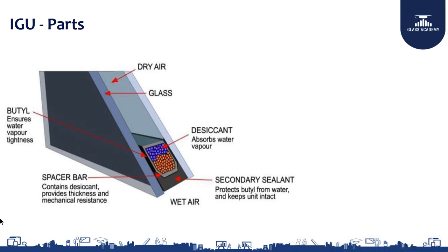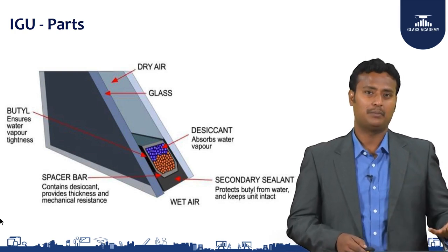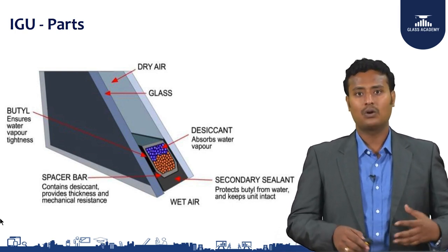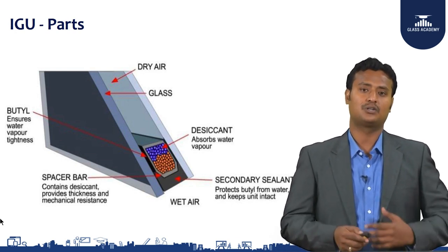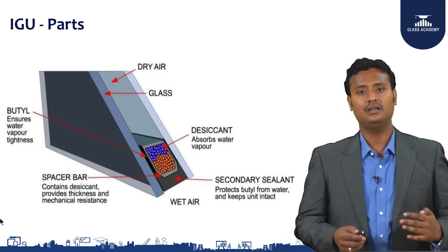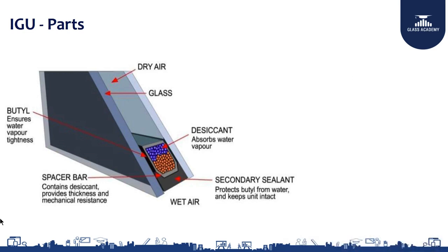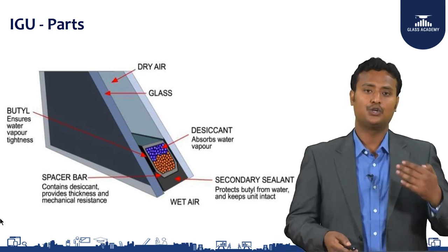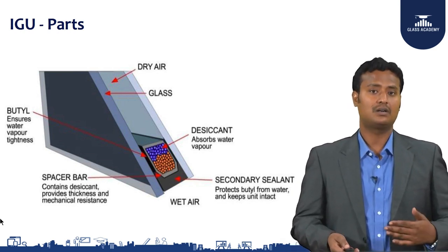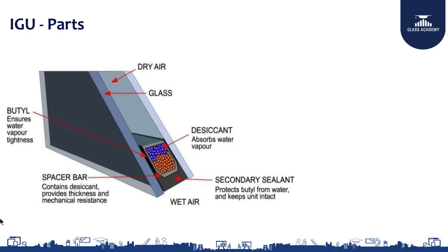Next is the secondary silicone, which basically protects from exterior conditions like water vapor, chemical vapor, the rainy season, and sun exposure. To protect against water getting inside, the secondary sealant gives structural strength to the IGU, and it prevents abnormal conditions like water, humidity, hot gases, fumes or chemical agents from penetrating inside the DGU. So the secondary silicone prevents those abnormalities.